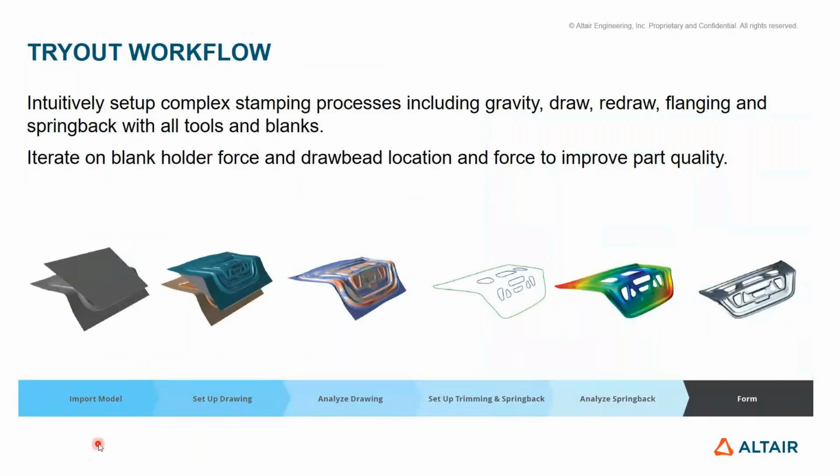So this is the general procedure. First you need to import the model, set up the drawing, analyze the drawing, and run the trimming and spring back, and analyze the spring back simulation.